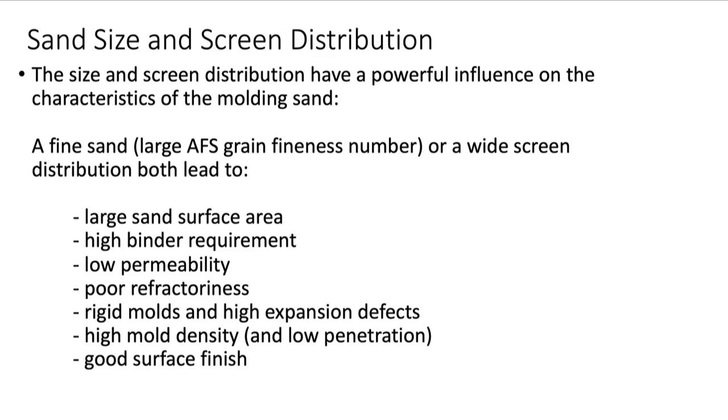Poor refractoriness. Finer grains heat up more, so they get to a higher temperature, and they're more likely to break down with temperature.